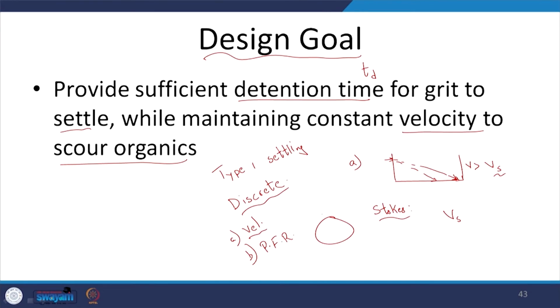Again, how can we get that? We know that due to gravity it is going to be pulled down, but there will be drag resisting this, and also buoyancy, right. So, if you balance these out and look at the relevant calculations, you will get the settling velocity, but again we will look at this in greater detail soon when we look at sedimentation.